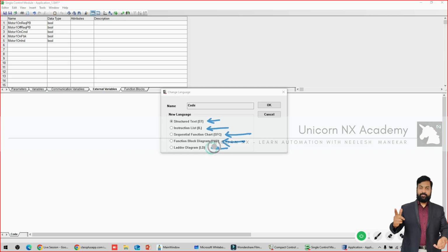And a ladder diagram, which gives you the feeling of an electrical drawing with contacts and blocks. Across all these, FBD and ladder are the most popular and commonly used across all manufacturers. For complex loops, you can use structured text. Wherever you have flow control or sequences, you can use SFCs. Instruction list is used by some programmers who are comfortable with it, but it needs learning the coding syntax and parameters, so not everybody is comfortable with that.